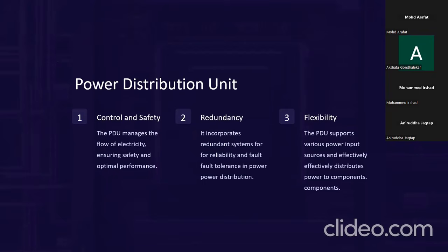So the components, the bus bars, the proper torque that you are tightening the bus bar with, the sensor components or the fuses for safety, you have to select those components carefully based on the power requirements, like how many amperes or how much heat is going to be generated at the power distribution unit or at that particular point. Based on those things, you should select those components.